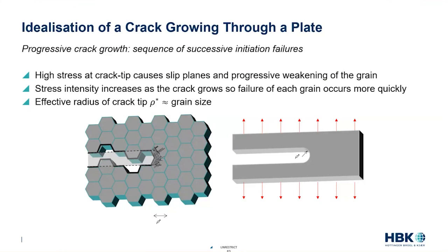The moment I make that assumption, I now have the ability to have a finite radius crack tip. I can predict the stresses in front, around, and behind that crack tip in great detail. It's no longer a stress discontinuity. In addition, once I have those actual stresses, I have the ability to go off and account for plasticity, both the loading and unloading, and look at things like residual compressive stresses due to plasticity in front and behind the crack. So it gives me a lot of capability of going in and doing this crack growth without any sort of assumptions in crack closure. I can model that directly.